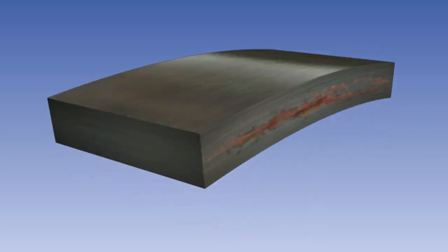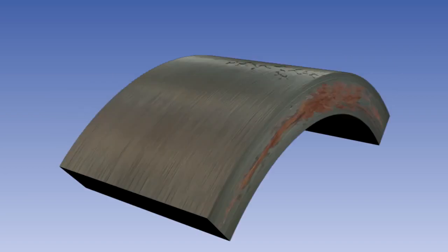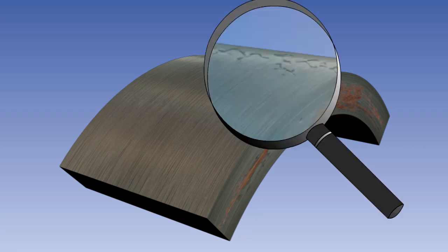Repeated, fluctuating stresses cause separation of the grain boundaries, accelerating the spread of corrosion. As a result, higher stress concentrations can occur in the remaining sound material, thus producing cracks which can spread, leading to component failure. This is a very dangerous form of corrosion, as detection is difficult and serious weakening can occur before any external evidence is visible. The only surface indication may be a series of hairline cracks, probably only visible through a magnifying glass.